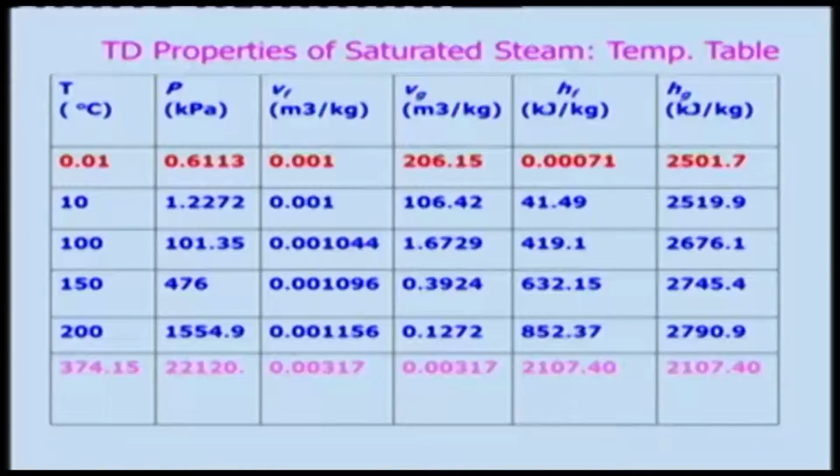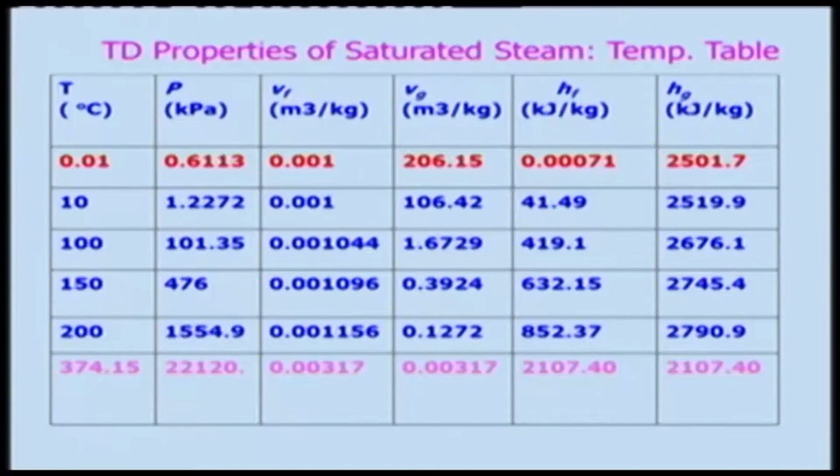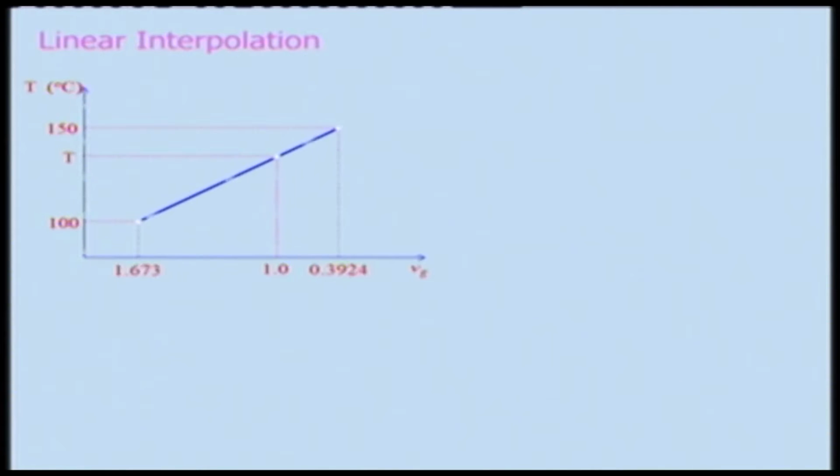If you look at this table, all this data is not linearly fitting, otherwise you could have an expression and do that very beautifully. You need not worry about the steam table or the refrigerant table and put the data in tabular form if it were linear. Keep in mind that the relationship between these data cannot be expressed in a linear form, but we will use a linear interpolation between the two data points just for approximation sake, because we do not have any better way. As the interval will be small, that is good enough for a linear interpolation.